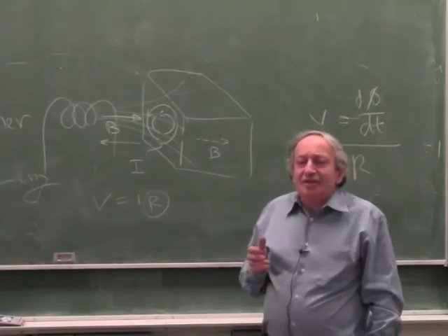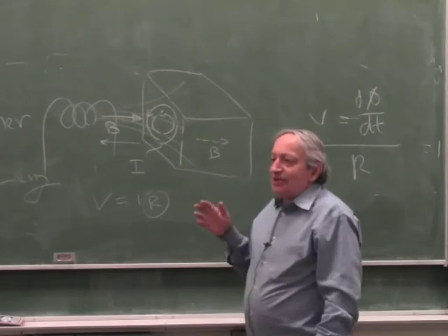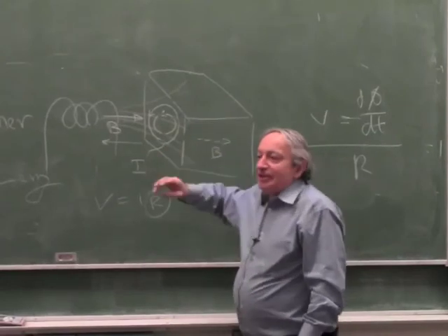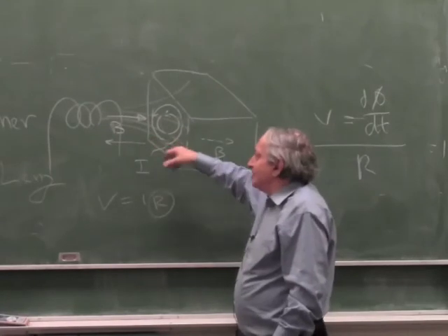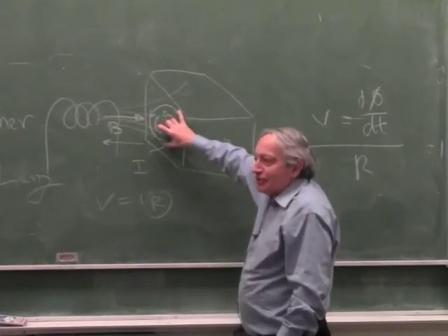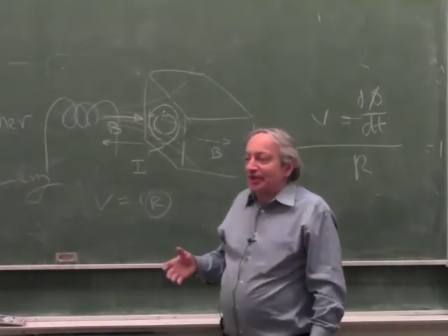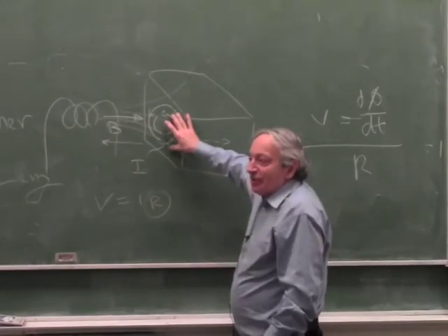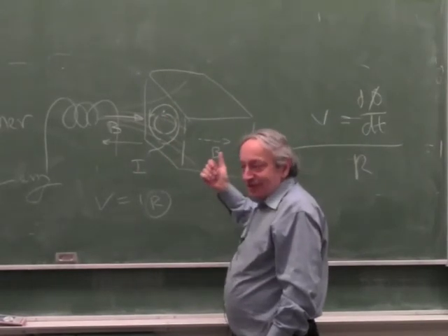Okay, so now you start saying, how should I make the best shielding? I know it will never be perfect unless I have a superconductor, and you quickly realize that if you made it all of steel, it will be good, because steel has a high mu. It will be good to make a strong magnetic field, but steel is not such a good conductor, so it has high resistance. There will be a voltage drop. If you make it all of copper, it wouldn't be able to stop very slow magnetic fields, because at very slow magnetic fields the induced voltage is very small, and for a DC magnetic field copper will do nothing. The magnetic field will go through. Right? So what do you do?